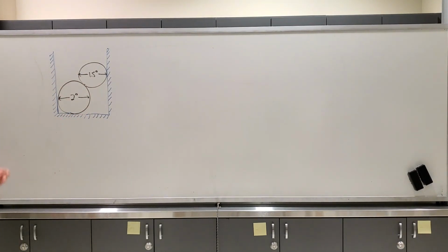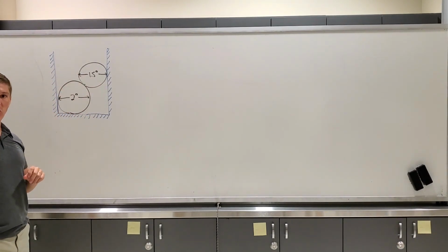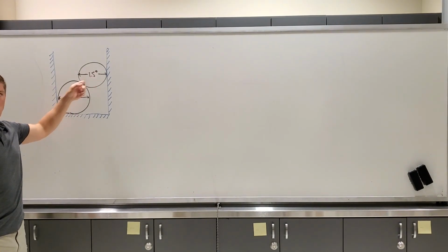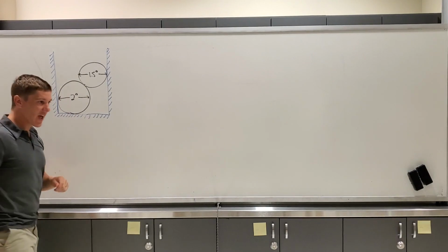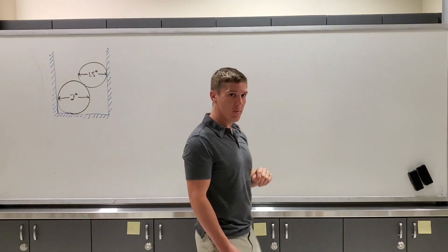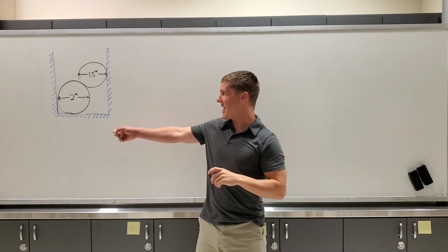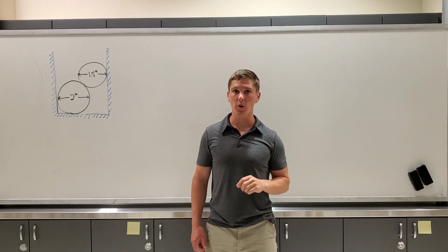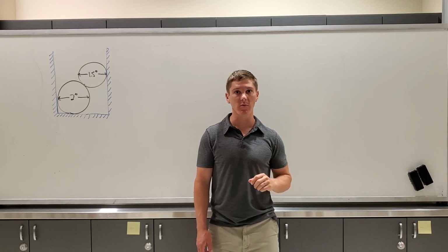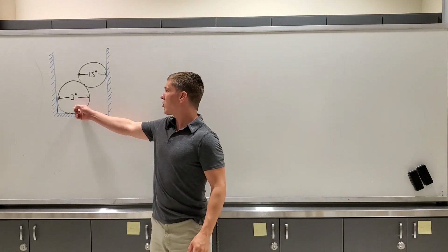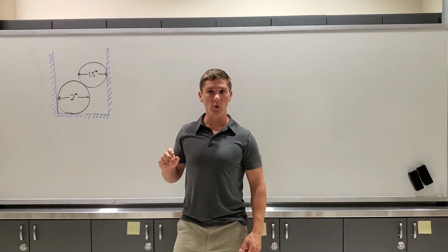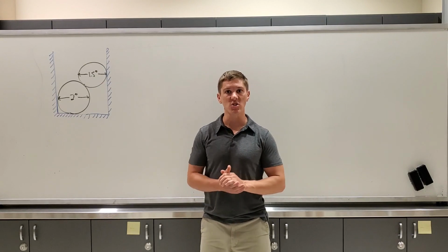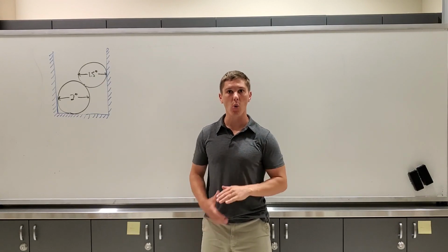So what we have here is two particles: the 2-inch steel ball bearing and the 1.5-inch ball bearing. In lecture, we said that for two-dimensional problems with n particles, in general we will have 2n equations of equilibrium. In this case we have two particles, so n is equal to 2. So in a two-dimensional problem, we will have a maximum of 4 equations of equilibrium.